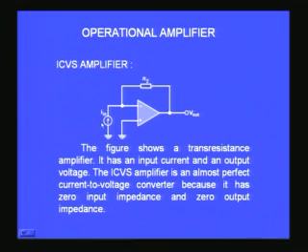So if I have some sensor which produces a current, the best method I could use is to connect that current to this type of circuit, so that the output becomes a voltage. The current is converted into voltage. Effectively the amplifier acts as an ideal resistance.